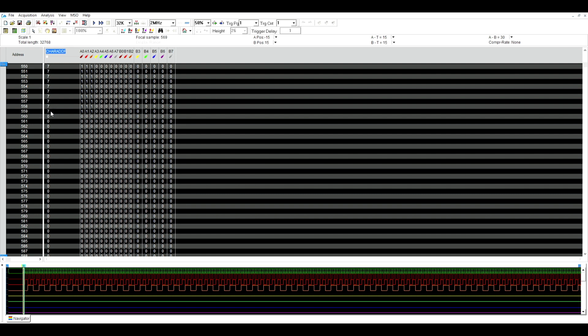So it has to be 0 for 80 clock cycles. Why? Because remember, each token line has 40 characters, and you need then to print the first byte of each of the 40 characters. So that goes from 0 to 39, or 40 instances. But you need to do that twice for each byte, because you're printing the same byte twice. So this index has to stay constant for 80 cycles. So let's see whether this is the case.